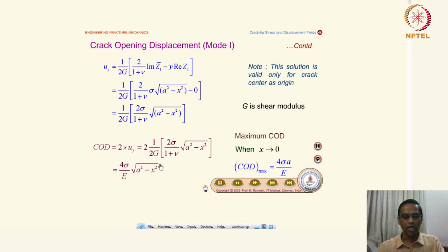That confirms that every crack tries to open as an ellipse. So the COD equation gives us an ellipse equation. That is also evidence that most cracks try to open as an ellipse, as we showed in all the animations in this chapter.